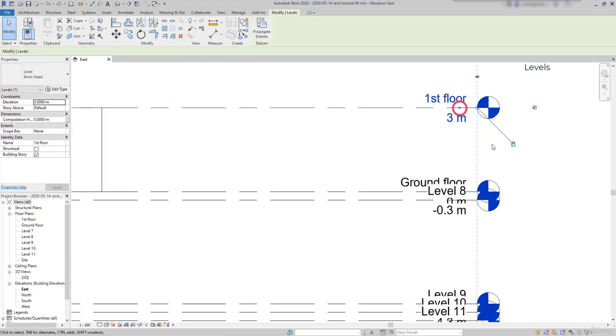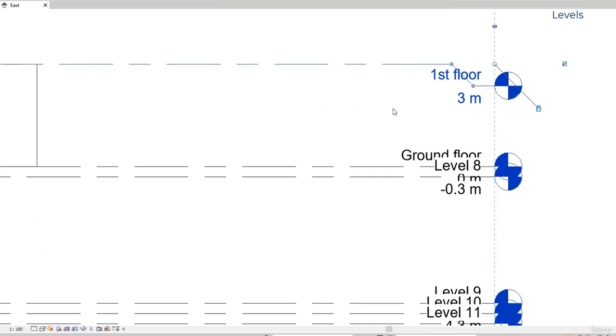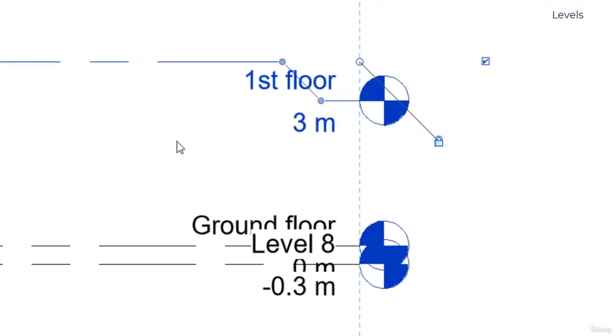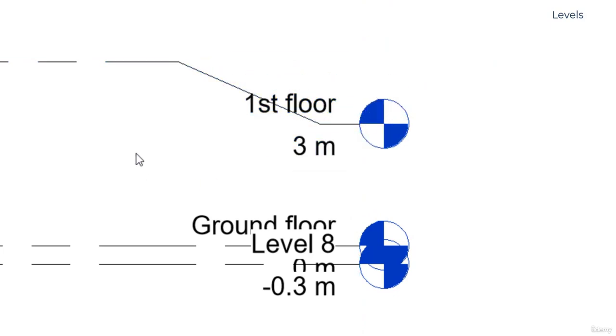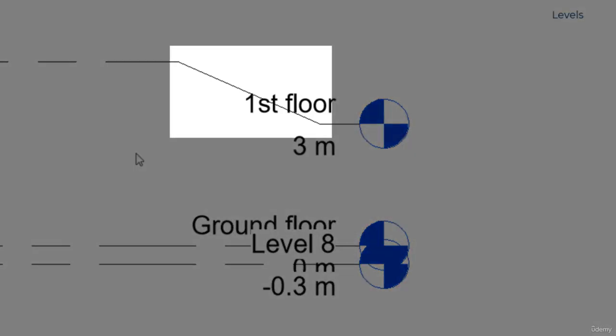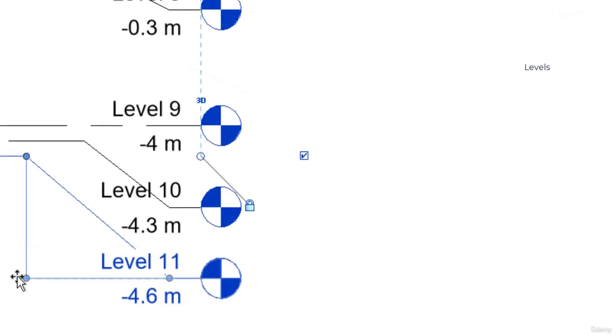You can notice this tiny jog that says Add Elbow. Click on it and you will see that the annotation leader is discontinued. So you can use these two control points to reposition the annotation of this level in the way that's better. You can keep that middle line diagonal or vertical like I show you here.